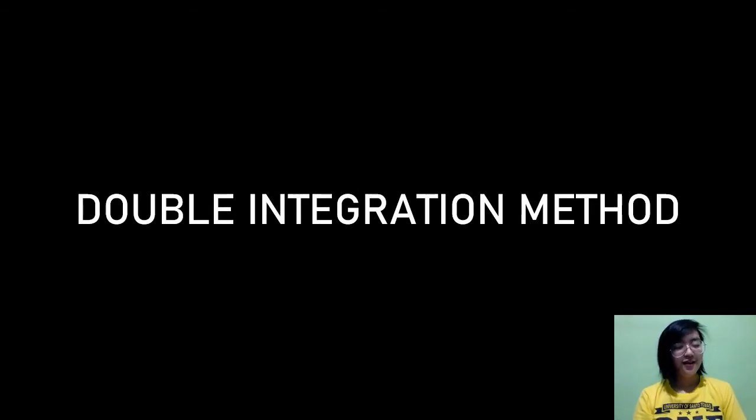Good day, everyone. I'm here to discuss the first classical method, which is the double integration method, also known as DIM. So, what is DIM? The double integration method is an analytical approach wherein the equation of the deflection would be established from the moment equation by integrating it twice, hence where the method got its name.